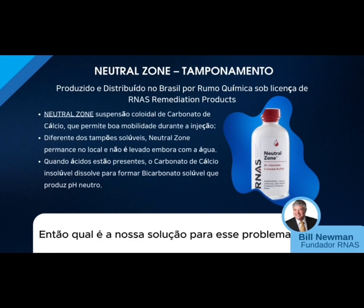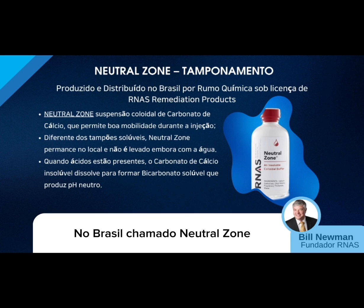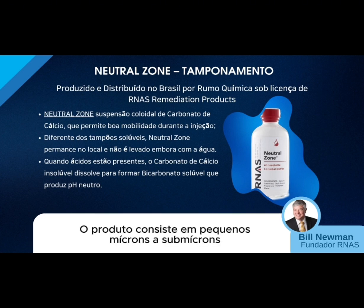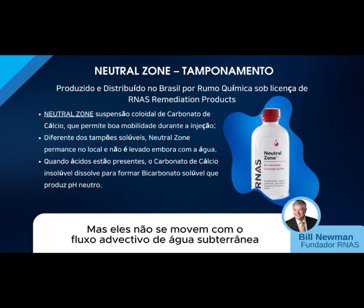So what is our solution for that problem? We make and sell a colloidal calcium carbonate buffer in Brazil called Neutral Zone. The product consists of small micron to submicron calcium carbonate particles, and we're able to inject those and make them mobile during the temporary circulation or injection, but they don't move with advective groundwater flow.